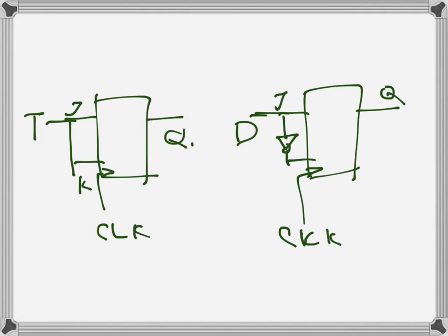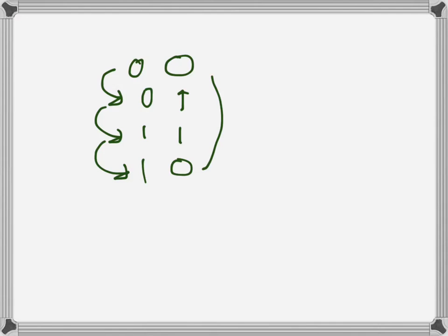So if I want to make a counter using D flip-flop, I have done it before, but I will talk about it again slowly. So here we just want to make a 2-bit gray code counter. So 0 0, 0 1, 1 1, 1 0, and back to 0 0, that's the 2-bit gray code. We want to make an up counter using D flip-flop here. So it should count like this, from here to here, from here to here, and then from here to here.